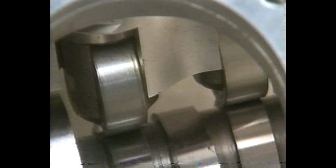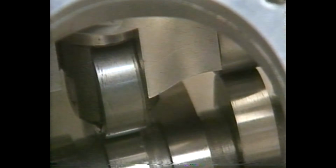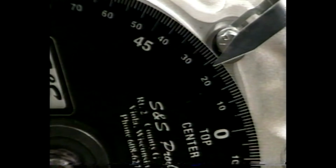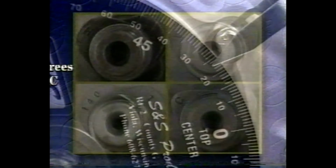Moving our dial indicator over to the front intake valve lifter, we find where the front intake cam lobe begins to open the inlet valve. We take our degree wheel reading from the point where the front intake lifter leaves the base circle by 53 thousandths of an inch and starts to lift the front intake valve off of its seat. Our degree wheel indicates that this event occurs at 23 degrees before top dead center.